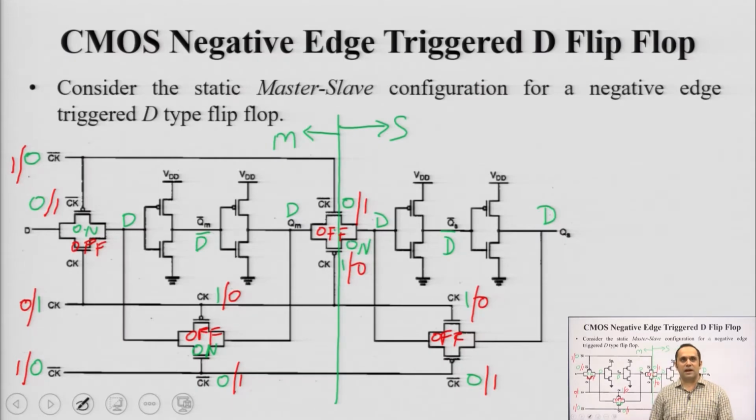If you look at the entire circuit, all this circuitry is required only for storing 1 bit of data. So, the major drawback of this type of circuit is the amount of circuitry, silicon area or the number of transistors which are required here. If the number of transistors is higher, a transistor which is a capacitive device is going to have some amount of delay associated with it. So, as the number of transistors increases, the amount of delay and power consumption also increases.